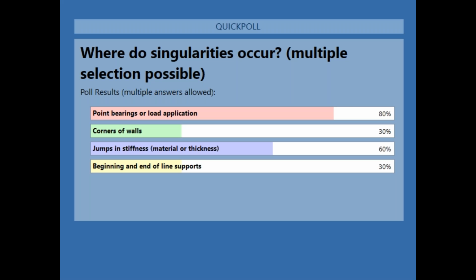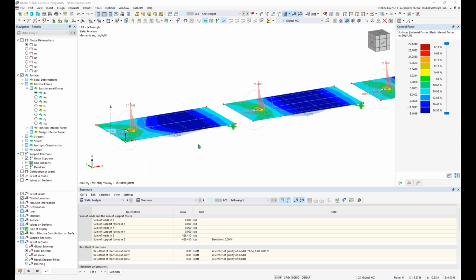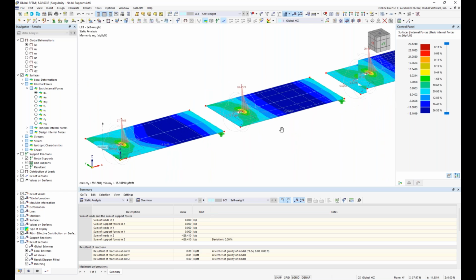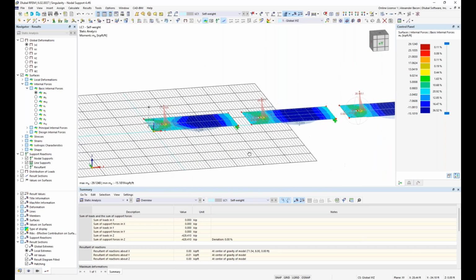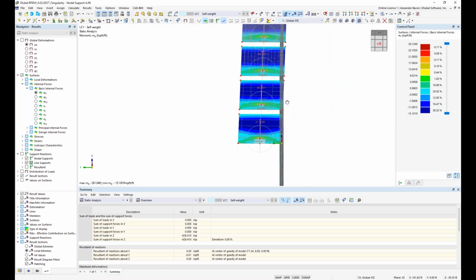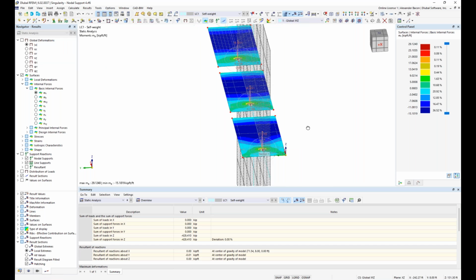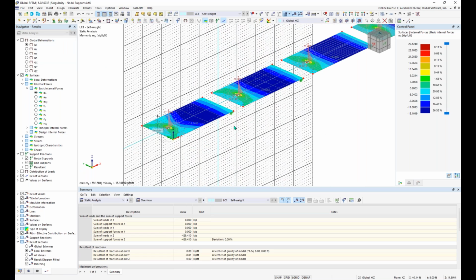So whenever you have a corner, let's say, of a wall feeding into a surface, for example, I want to change my work plane here, and I also want to move it over a little bit, like that. So you can change your grid work plane using these buttons up here, and you can change the origin of the grid work plane using this button.